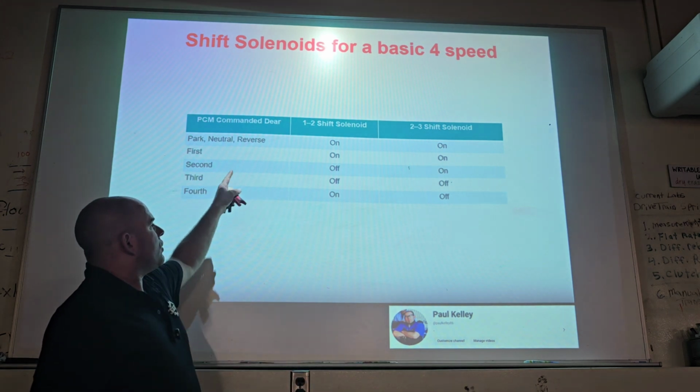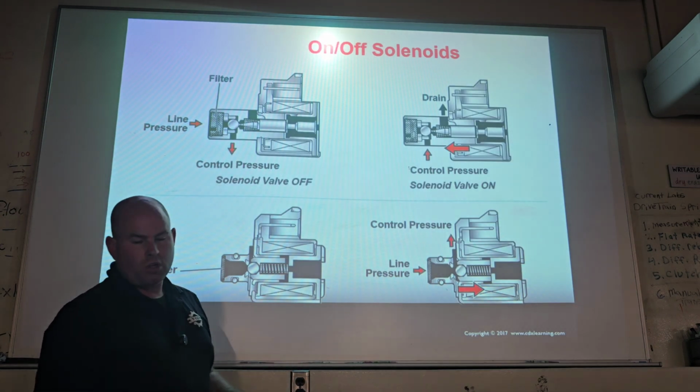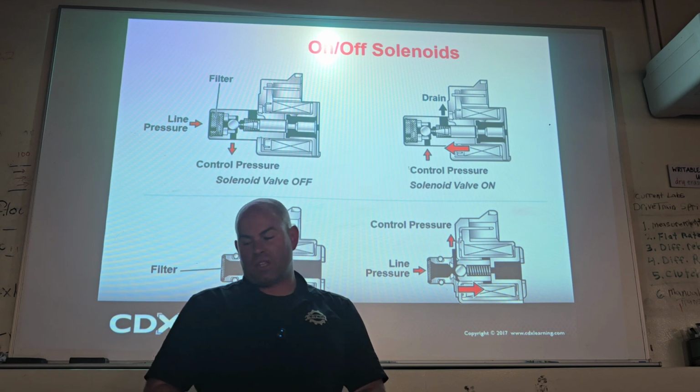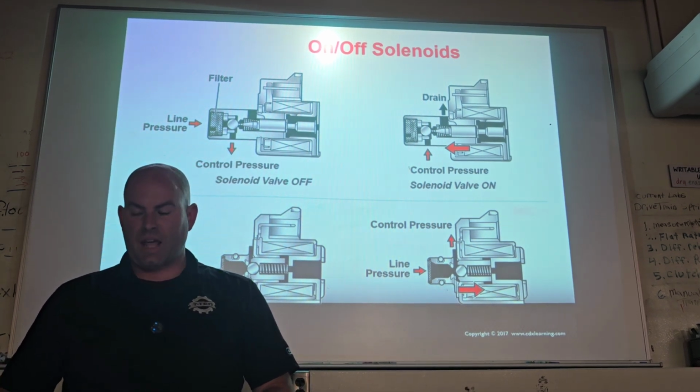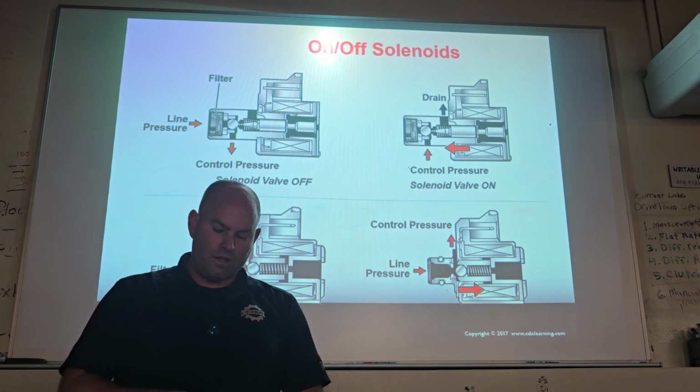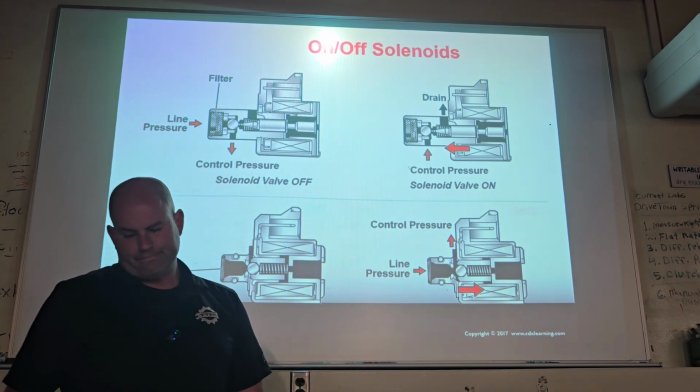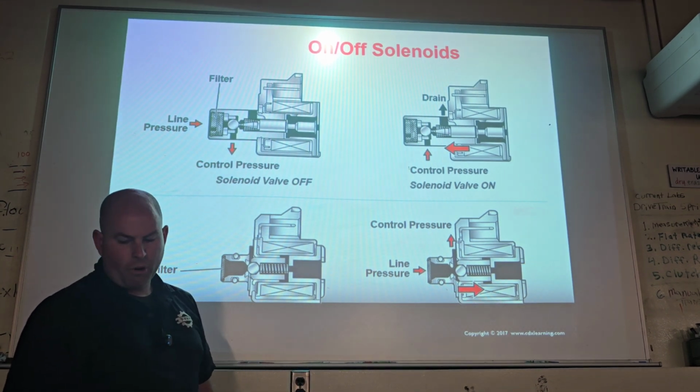So if you wanted to know if the shift solenoid was flowing, totally different, difficult diagnosis. Same with the injector, right? You could test an injector electrically pretty easily, but actually to test it for flow, different kind of issue. So got to know that it could be both.